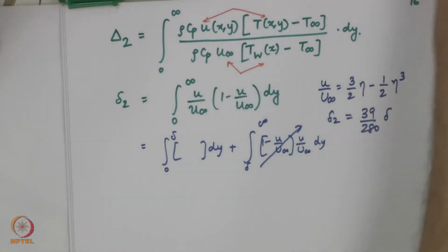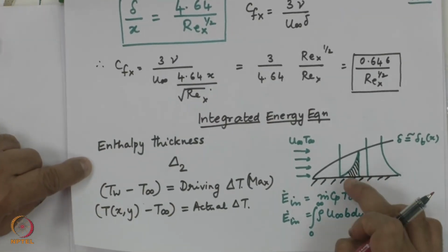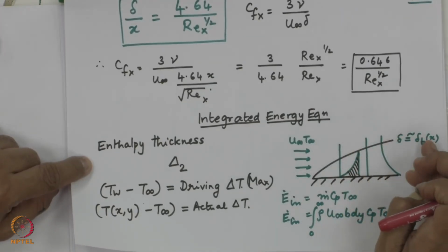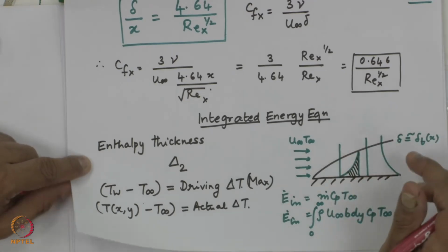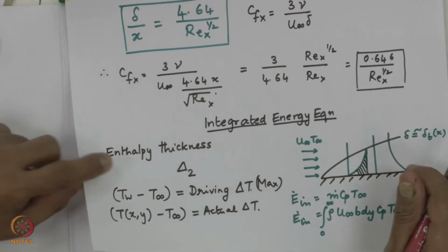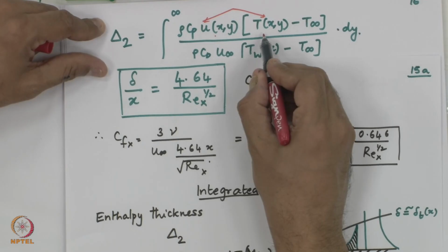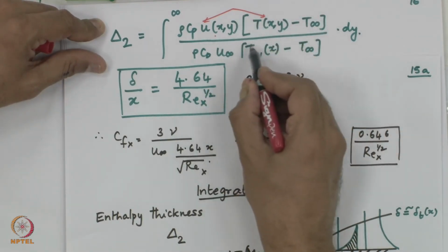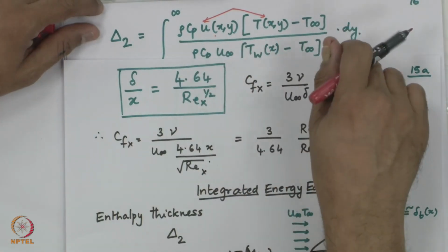This pair is going to continue to affect the heat transfer, it's going to go as a pair. That's why I said here I am taking delta equal to delta t, which means my variation in the boundary layer thickness, hydrodynamic and thermal boundary layer thickness are similar. One is not growing faster, other is not growing slower, which means when I have to evaluate this enthalpy thickness, u into delta t, profile for velocity times the profile for the temperature, these two profiles have to be multiplied and integrated.